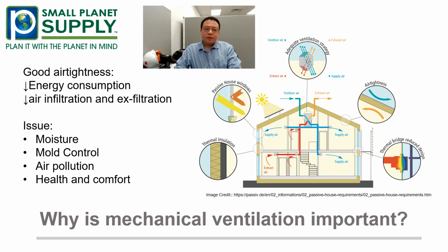So why is mechanical ventilation important? Nowadays the passive house normally has very good airtightness. As a result, it has very low energy consumption, but the air infiltration is low as well. So it will raise a lot of moisture, mold control, air pollution, health and comfort issues.